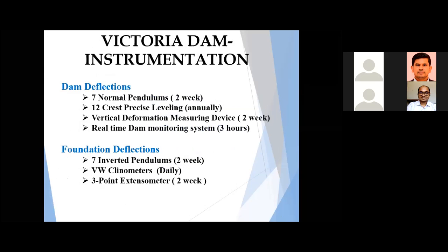Here, why these instruments are used: for dam deflections and foundation deflections, and what sort of frequency we are taking in instrument readings. Normal pendulums, every 2 weeks, like that.